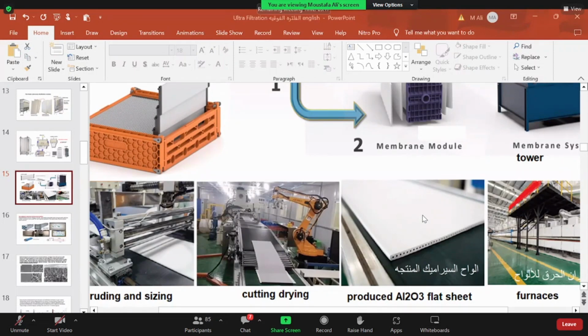This means it is vacuumed and filled with argon gas to avoid the complexation of nitrogen with the silicon and the carbon, the nitriding process. In such a case, it will damage the membrane or produce a very bad quality membrane.